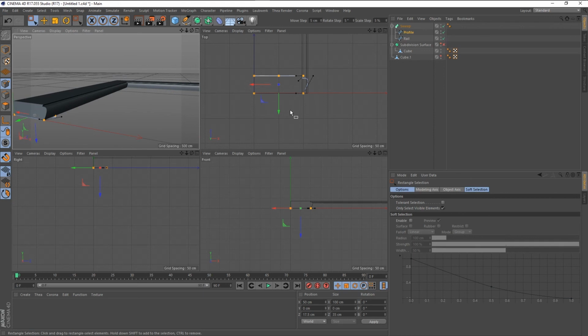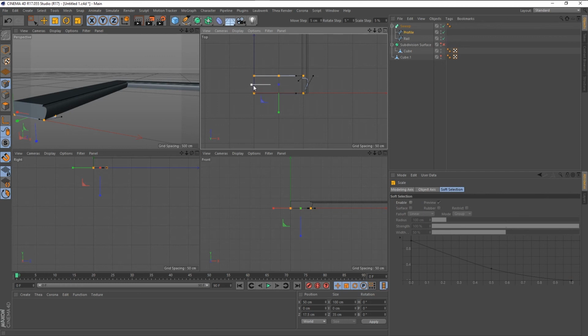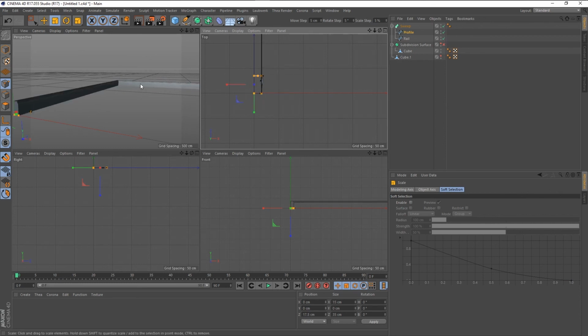I'm hovering over there. I'm not clicking in the thing. I'm hitting T for scale. Actually, I'm going to go to E for move. Move the axis point over here. Okay, and it snapped because my snaps are enabled. And now I'm going to hit T for scale again, and I'm going to drag this down, and what I want to do is cut that. Oops, now I got to turn off axis, and now we're going to scale the objects about that point. Now I can scale the objects about that point, and that could be the skirt board for going around a room in architecture.